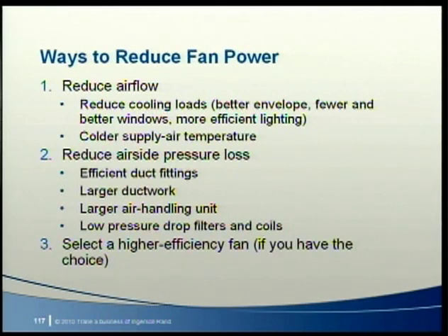Finally, the third strategy is to select a fan that has a higher efficiency for the specific application. But remember, as we demonstrated earlier, the right fan depends on the application. Forward curved or airfoil, housed or plenum, belt drive or direct drive, single fan or fan array, they all have their advantages and drawbacks.